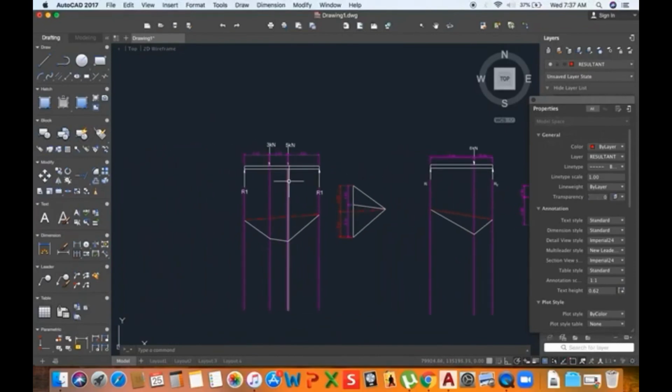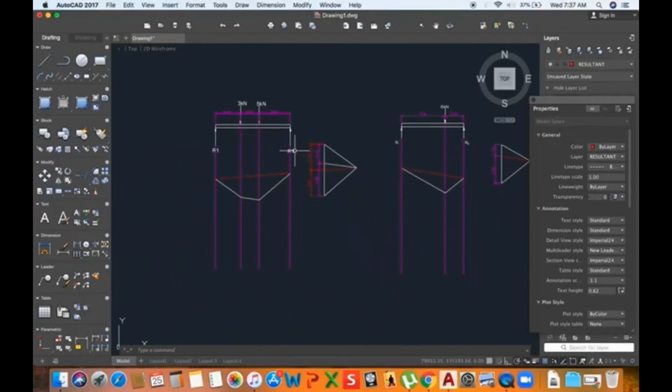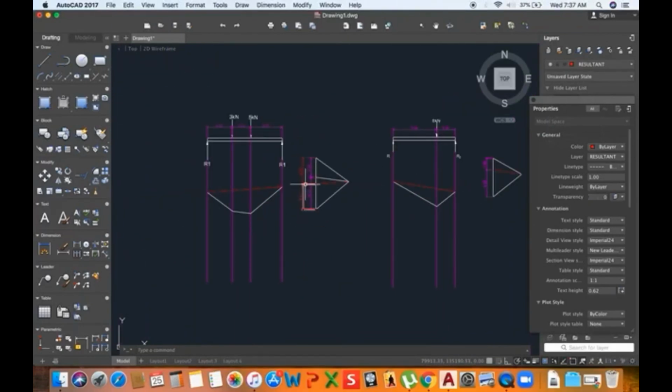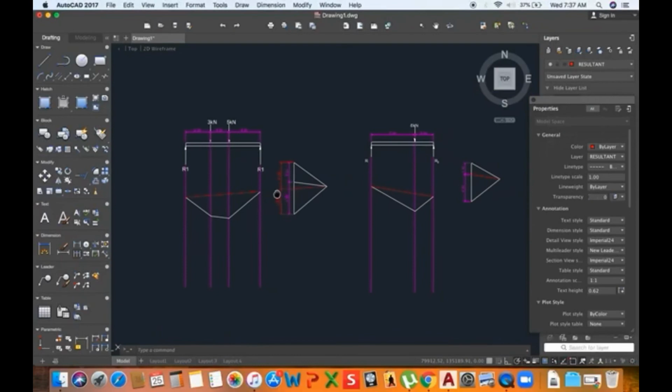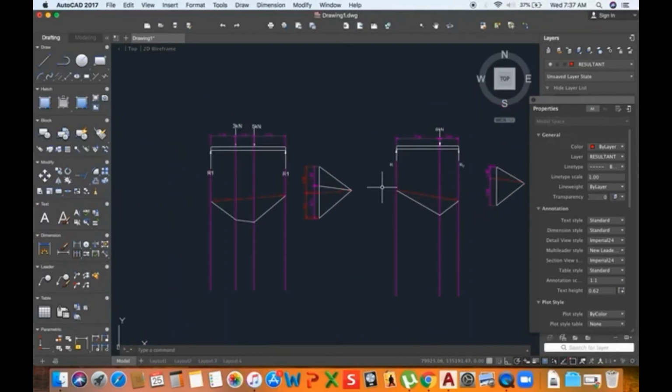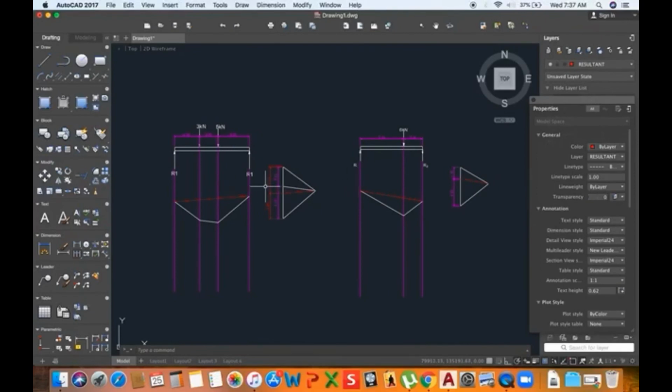And for episode 9, you would realize that these are the answers that I got for reactions 1 and 2. So the graphical means is a very accurate means of solving for the reaction forces R1 and R2 in any simply supported beam. It doesn't matter the number of forces.